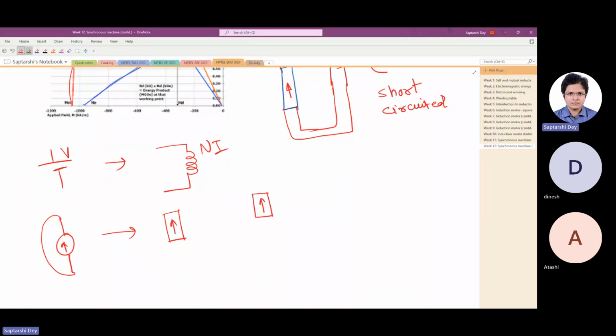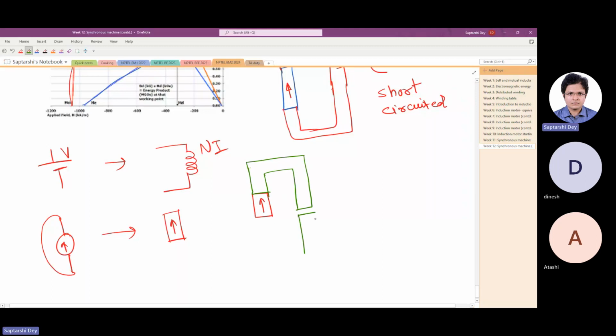Now, you cannot keep a magnet in a keeper throughout your life, because in that case, how would you use it? If you have to use the magnet, you have to take it out of the keeper, or maybe make a cut in the keeper where you can get the magnetic field. Now suppose this is where I made the cut in the keeper. So there is an air gap. Let us say the length of the air gap is Lg, and the area of the air gap is Ag. Say throughout the circuit the area is the same. The length of the magnet is Lm, and the area of the magnet is Am.